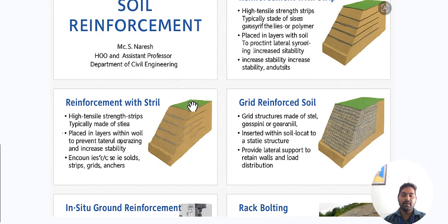So what happens when I apply the load here? Before placing the reinforcement, if you load here, maybe it is unable to bear the loads, but after placing the reinforcement strip here, when you apply the same load, it can resist that load. So this is a reinforced earth.